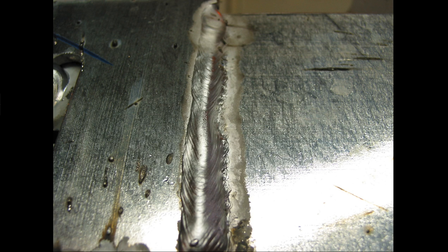And remember this always. And now you can almost use what I'm about to tell you across the board on every single welding process. We want to weld it once, hot, and fast. There's only a few exceptions to that everywhere in the welding industry. The quicker you can liquefy a material, homogenize a material, and have it fuse back together and solidify, the better. With, like I said, only a few exceptions.